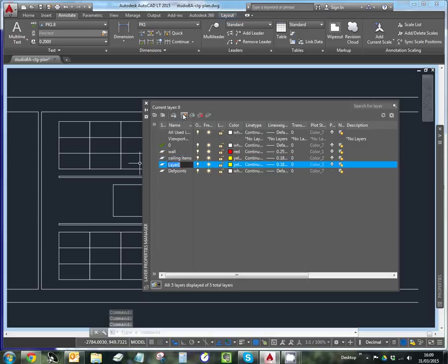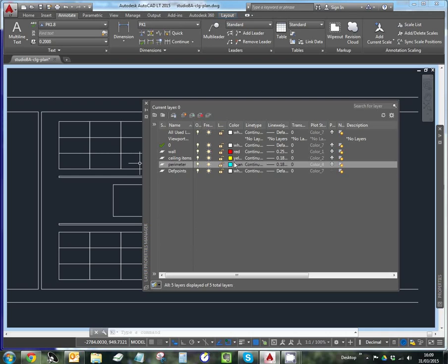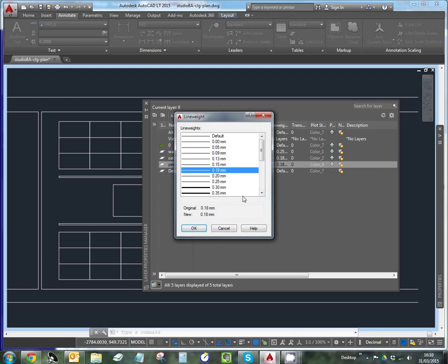And we could do with a layer that deals with the ceiling perimeter. This gives us the opportunity to pick that out in a heavier line, we'll see later. So ceiling perimeter, let's make that cyan, that'll stand out on the page, sort of reflecting a wider, thicker pen. We'll use 0.35.